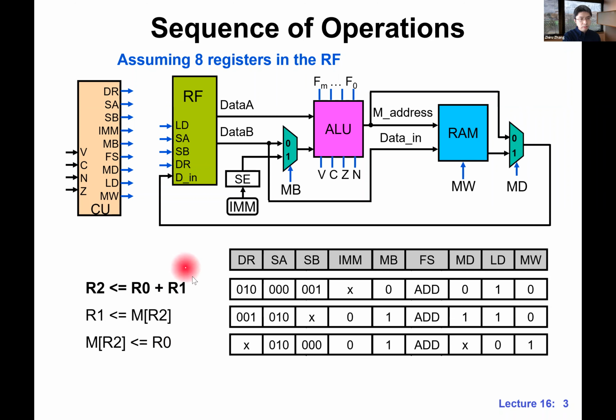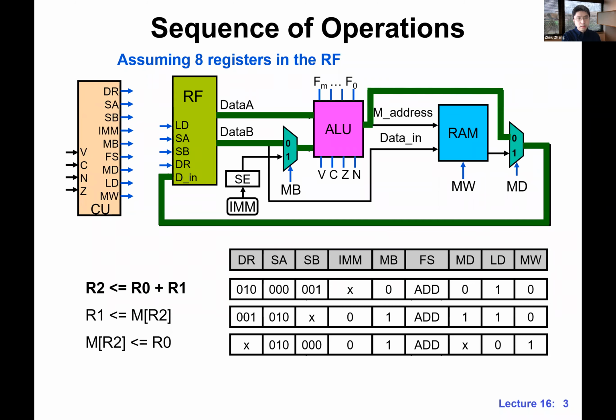If you look at the first one, this is really arithmetic. We're doing addition here. Just want to make it clear, I'm highlighting the information flow, or data flow, through this microprocessor. Basically the lines right over here, the heavy lines in green. This is how the data will flow for this specific instruction when you're doing addition. Again, we read out from the register file.